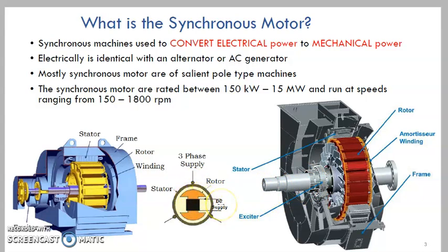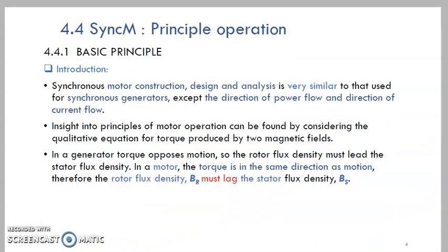And why do we use a DC supply? Because we can adjust the current flowing into the rotating poles here. If we use a permanent magnet, that also works, but we are not able to adjust the amount of current flowing into the poles, so the magnetic field's intensity cannot be adjusted, which means the speed or power of the motor cannot be adjusted. That's why we need an adjustable DC supply.